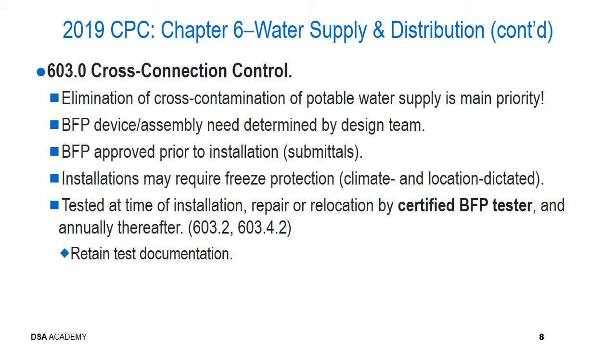Backflow prevention devices are required to be tested at the time of installation or repair or relocation, and these tests are required to be performed by a certified backflow prevention tester. These are also supposed to be performed on an annual basis, but that particular requirement falls on the owner.